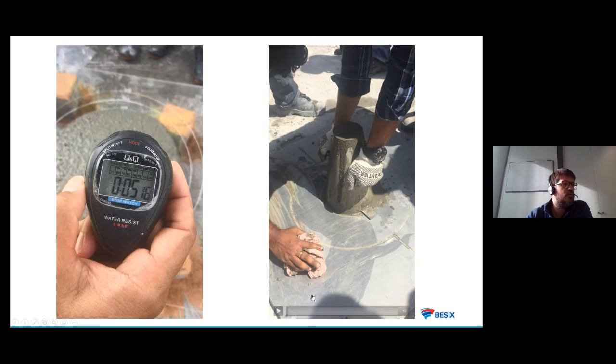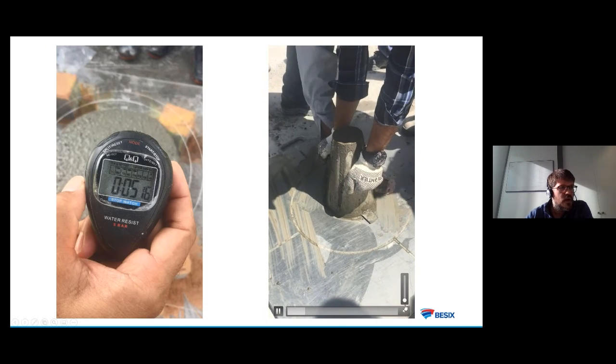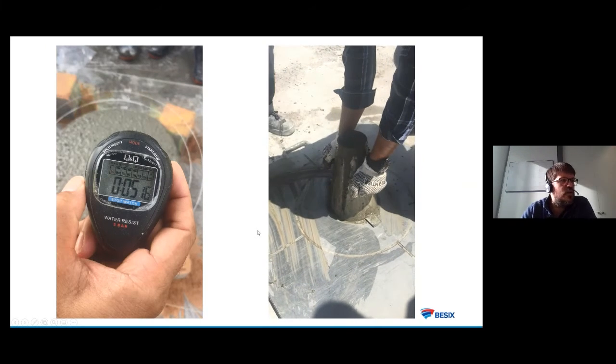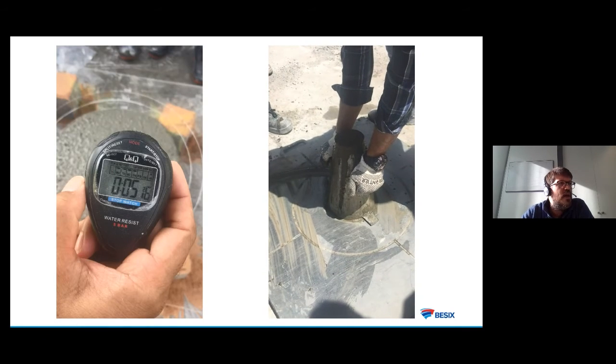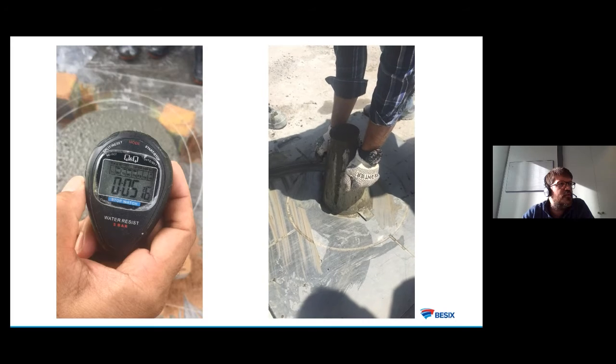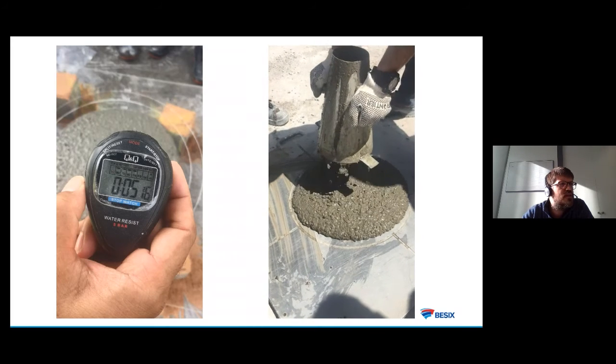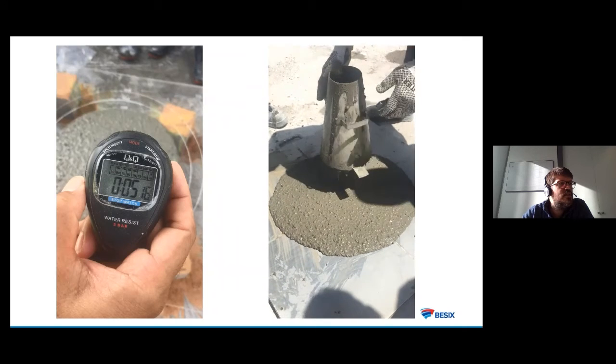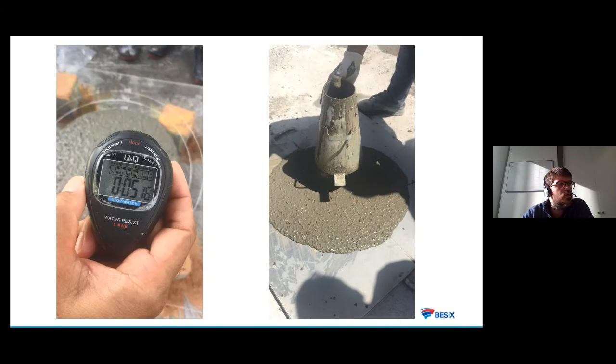You will see on the second video, it takes a little bit more time before they lift. But so you can see that you have the circle with the 500 millimeter, and here it will be less viscous than the first one, and you can see that it will take only 3 seconds to reach it. So you can really see the difference. You might think that it is a little bit too much fluid, but when you see the concrete, you can see that there is no segregation at all. This means that the second concrete is really a concrete that you will prefer to use if you have pumping to do for the concrete. It's a simple test to do, but it can give you really a lot of information.